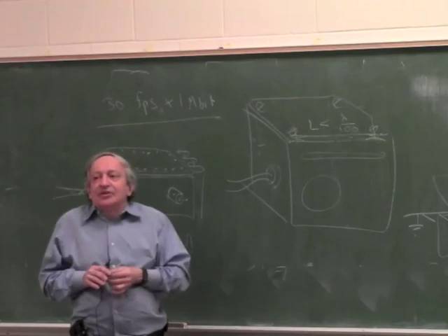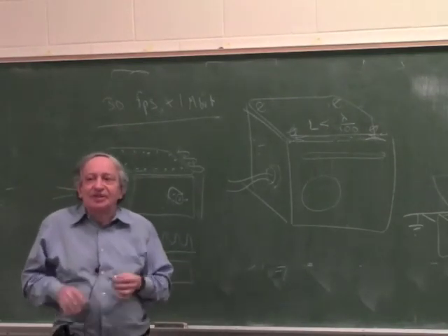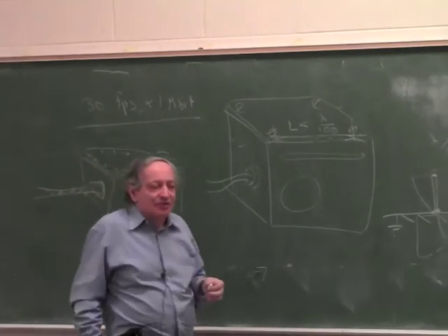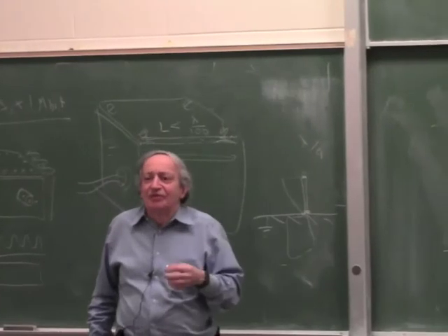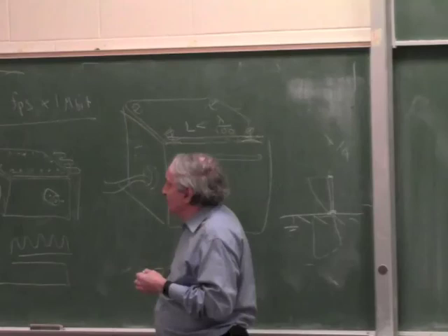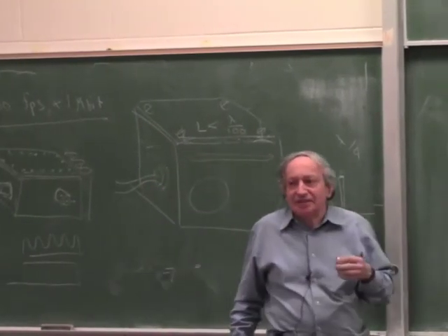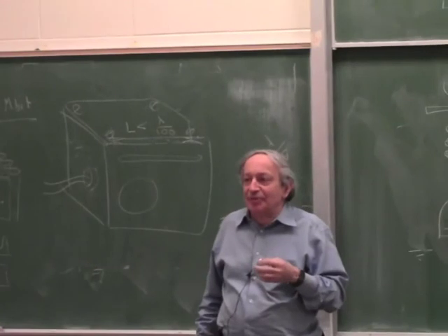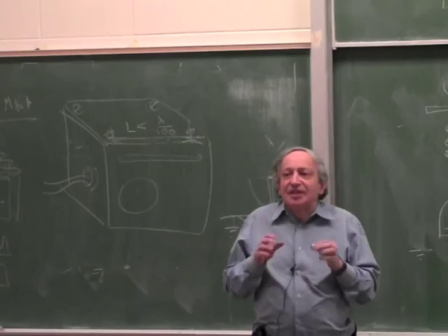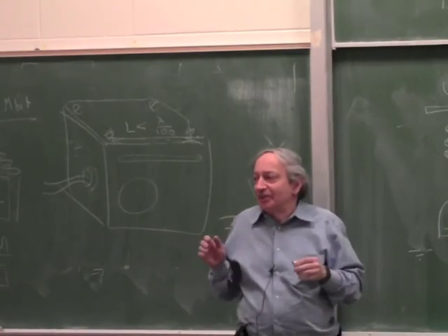Good. You also notice that in RF boxes, sometimes the box itself is silver plated or made of copper. It's not made of steel, it's made of a good conductor. For the normal things it's made of aluminum. For very high-end things it's made of copper, sometimes silver plated. Okay? Now why, if you look inside RF components, in the high end, everything is gold plated or silver plated.